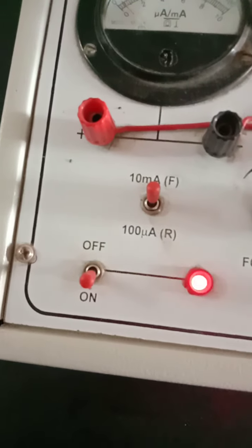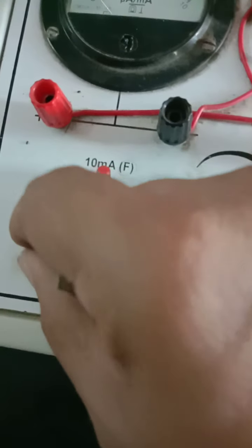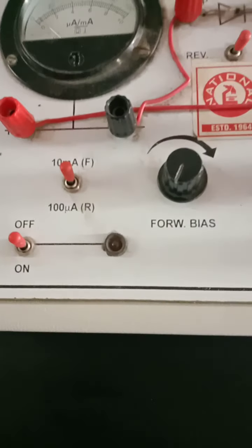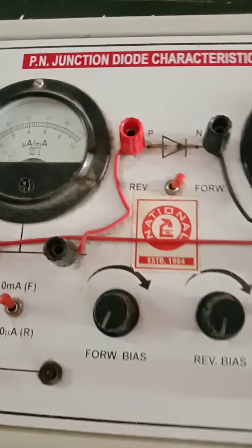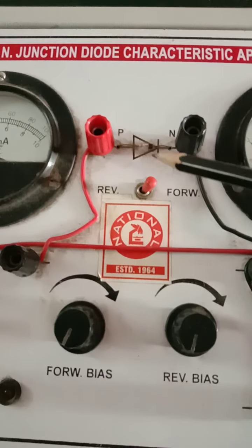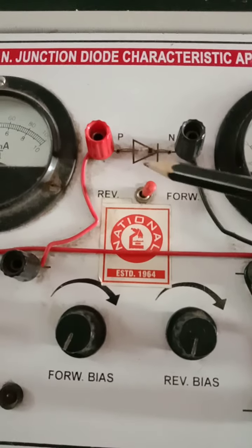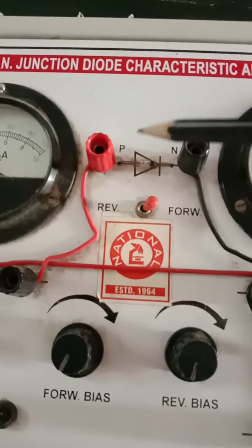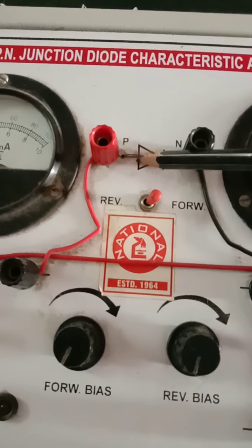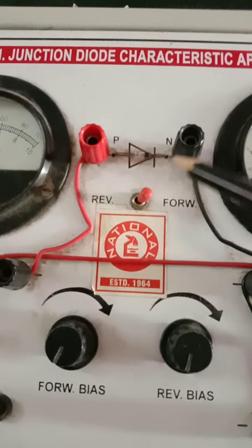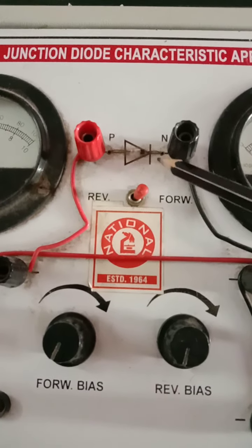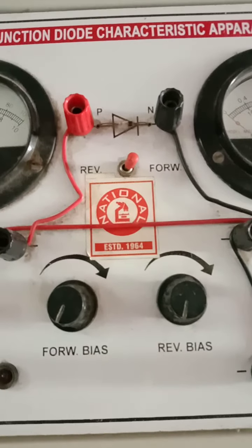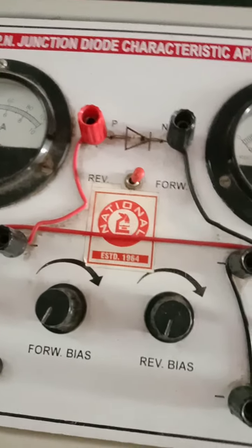the knob for on off. So it will be made on or off like this. So now it is off. This PN junction diode is always connected in the circuit in forward bias mode. That is, the P region of the diode is connected to the positive terminal of the source, and the N region of the diode is connected to the negative terminal of the source of EMF, and that's why it is called the forward bias.